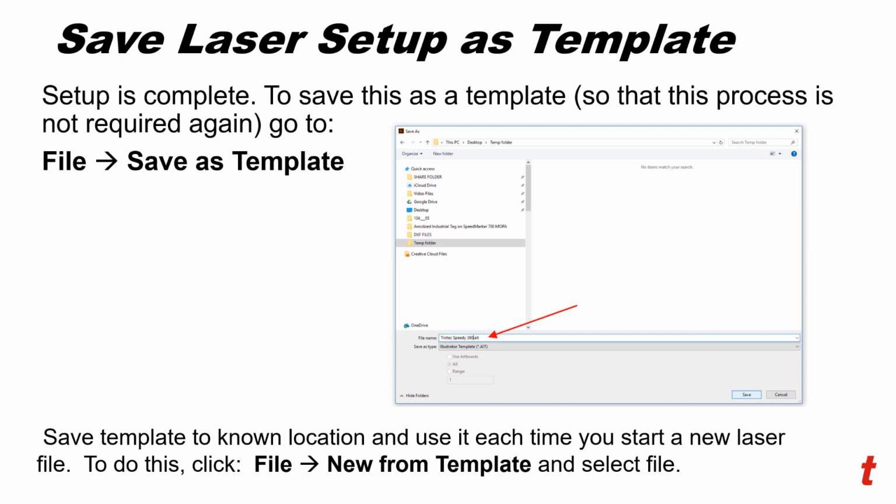What you will want to do is open up your template, and then you'll want to place their file into this template. I know it's tempting to select someone else's file if they email it to you to operate with the laser, and then just open it up. The problem with doing that is the attributes for their software setup are going to come with their design in that file. So if their line thickness and their colors are all set incorrectly, it may not work with the laser.